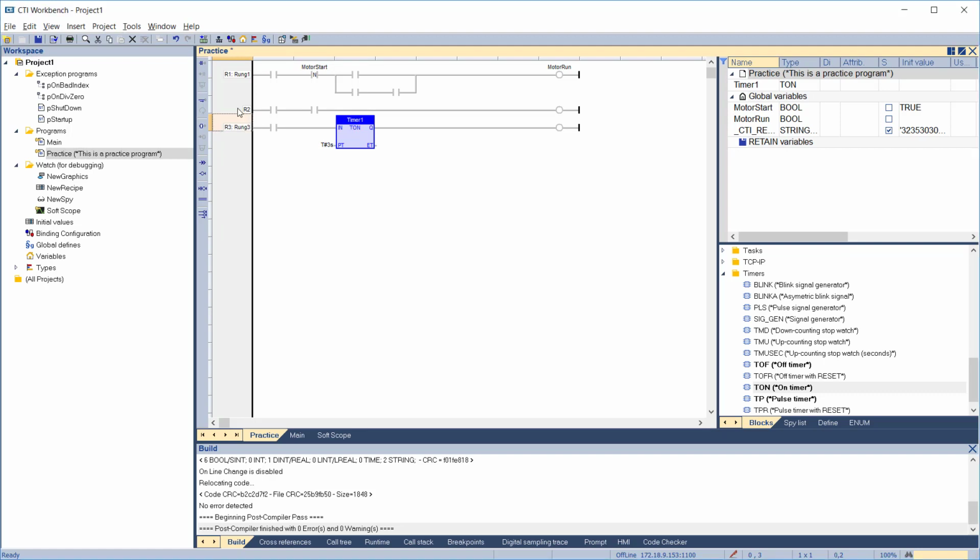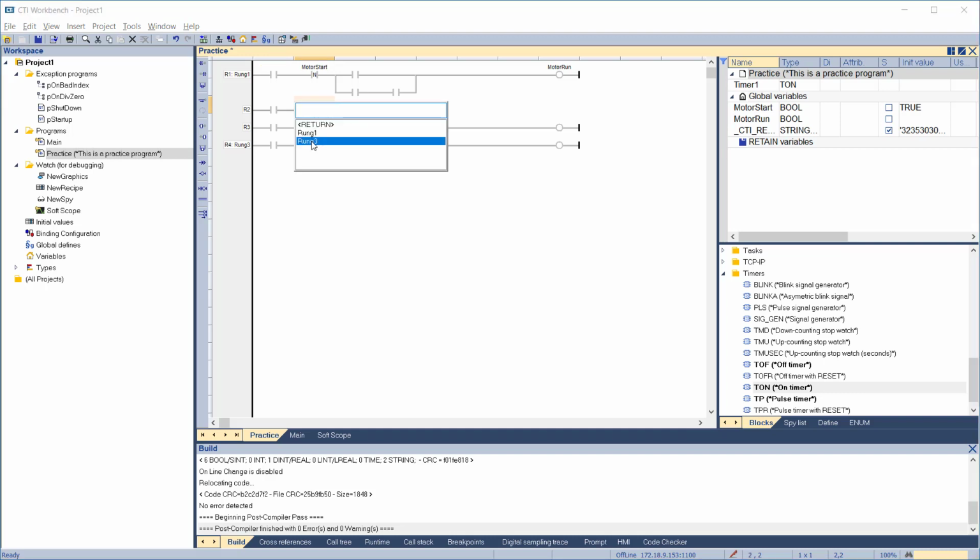Then go to the desired insertion point in your ladder, and click the Insert Jump icon. If you want the jump to be conditional, enter the desired contacts in front of the jump. Then double-click the jump instruction, and select the label you want to jump to.